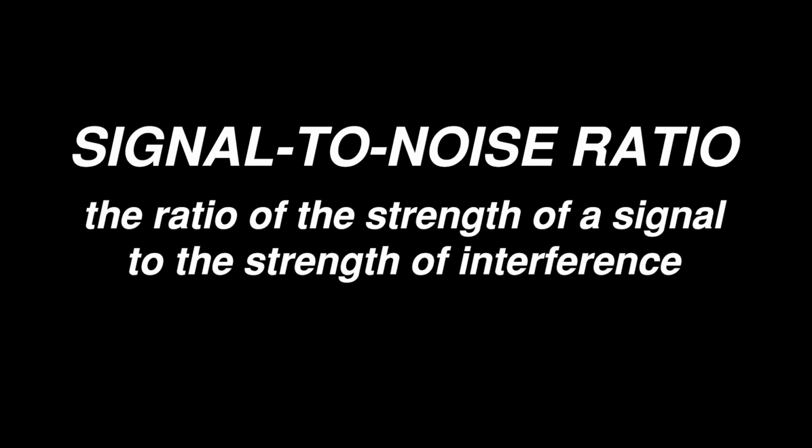We also want to set up the gain of the system to minimize noise. The signal-to-noise ratio is the difference between the noise floor and the signal. Generally speaking, the quieter the noise floor can be in comparison to the signal, the better.